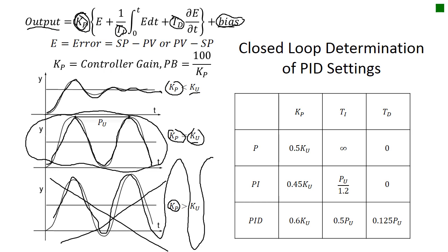So let's say we keep increasing our gain until we find that we're at that stable oscillation. Once we're there, we look at the time difference between oscillatory peaks. This time difference, the time between one peak and another, is what we call the ultimate period. So if I find my ultimate gain and the period associated with it, I can now calculate my proper values. Now, you have various different control systems.